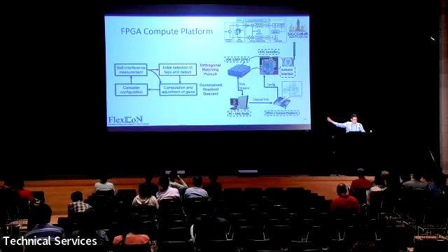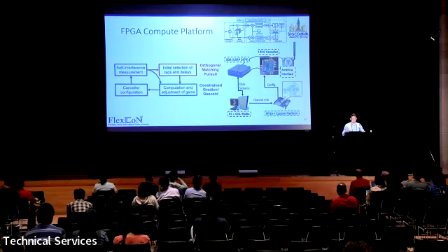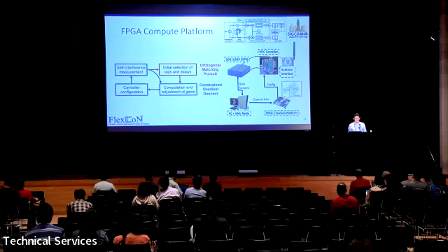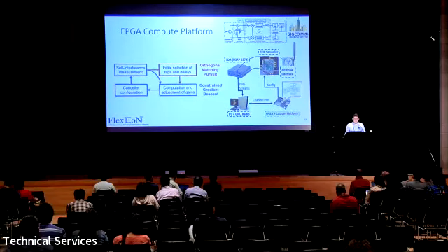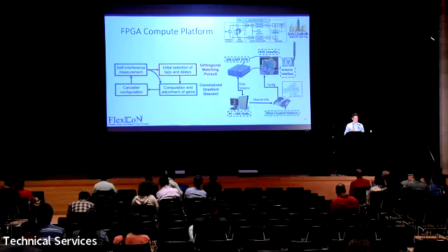For every packet that comes into the system, and I'm going to get to the communications in a second, we measure the self-interference that we're hearing. Initially, we do a one-time selection of taps and delay combinations. We select the primary settings we want to use, and then we compute the gains that we want to have on those taps in the filter. The FPGA configures the canceller and lets us know how we're doing. We measure self-interference again, and we iteratively adjust bit by bit until we get to the best cancellation we can get from this RF SIC.